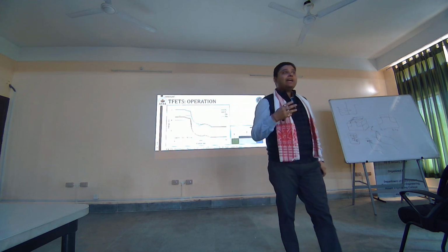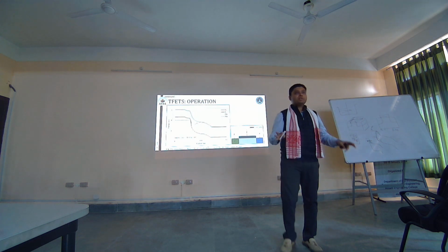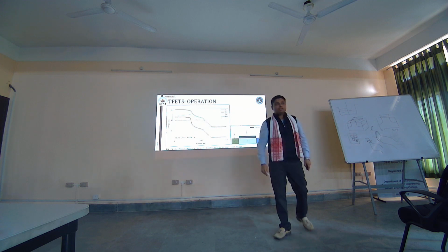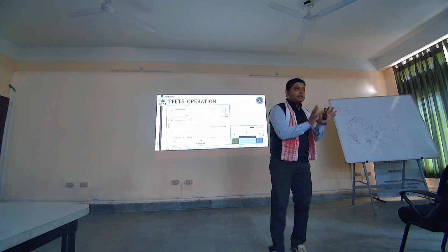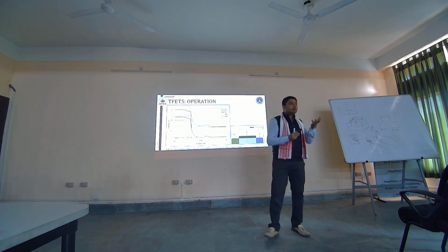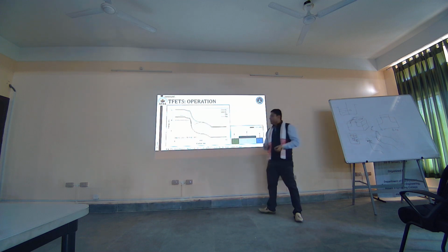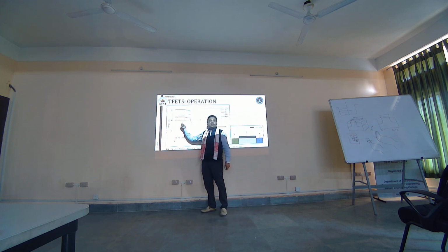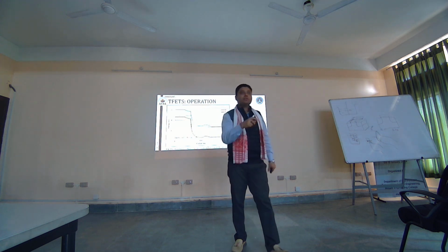whenever we say that carriers have tunneled, actually we are not saying it correctly, although it has become the convention of the teaching and learning process, because this is not a classical concept. Whenever we speak about tunneling, we have to be very careful that we use the word probability, because it is a probabilistic situation, right? So whenever we talk about tunneling, it means that the probability of finding the carrier on the other side of the barrier is finite. That is the actual interpretation of tunneling.